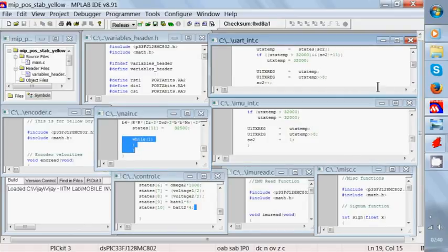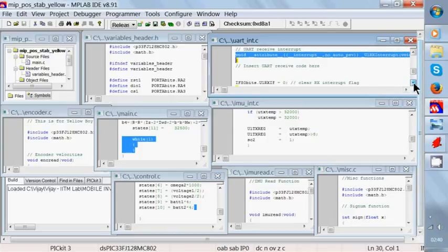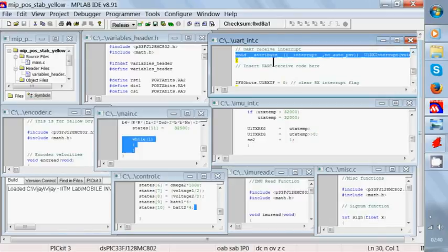And if there are some data received using the UART receive, there is a UART receive interrupt which occurs, and since sense has to be made on what the received data is, whatever your desired data identification code has to be inserted here.